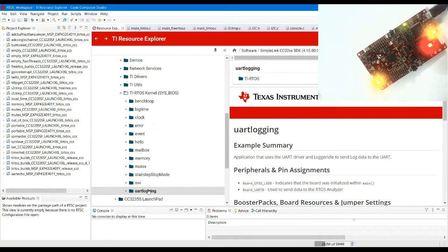So we create a handle for a particular UART initialization, and after getting the handle, we pass it on, and through that handle we pass on data with whatever we want to display on the UART console. So this particular application shows you how to use the UART driver, how to create that handle and pass on some data to show on the UART.